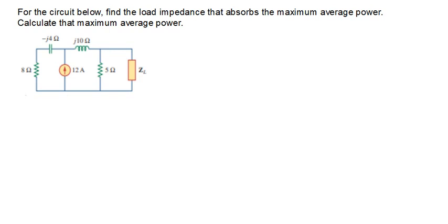The first thing I would want to highlight, and I believe we get this concept from the Thevenin and Norton part, is that if your load resistance is equal to your Thevenin resistance, then maximum power is going to be delivered to the circuit, provided these two are equal to each other. All right.